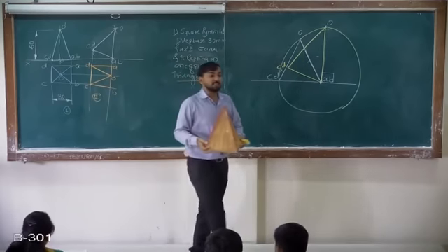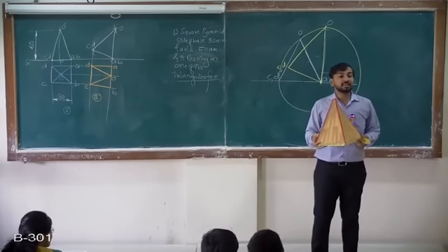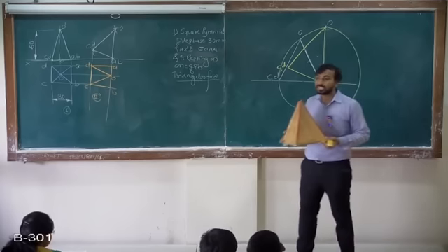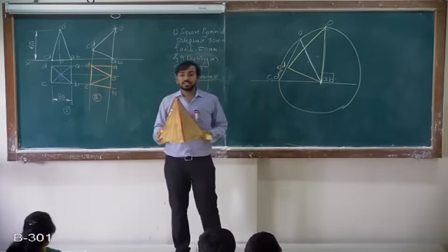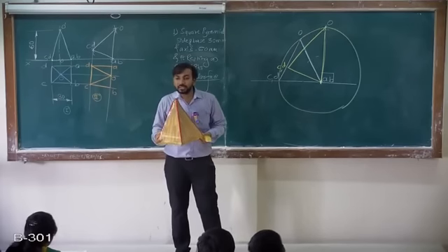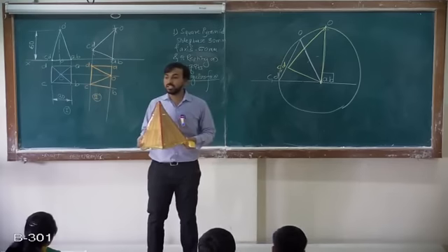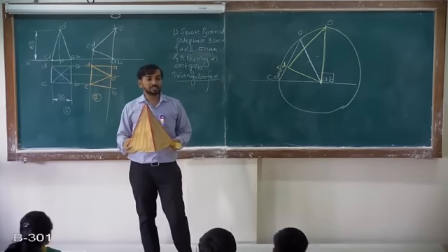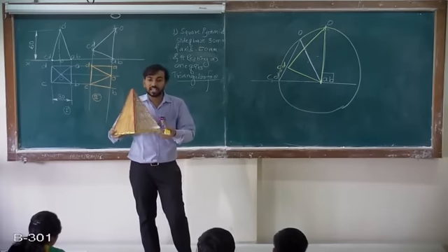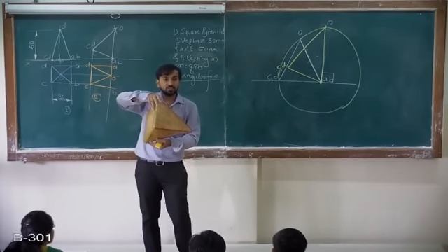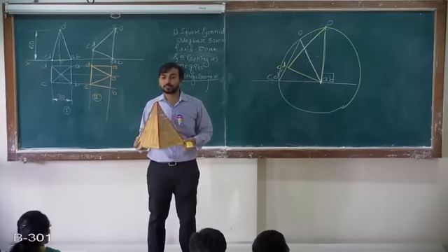So if it is simply said apex is at minima, then they should mention in the question detail resting on side or corner. If they are saying resting on slant edge for pyramid, for prism it is resting on longer edge or simply edge. For pyramid, the question is it is resting on one of its slant edge. So resting on one of its slant edge means like this. So I need to take resting parameter in first stage as corner.